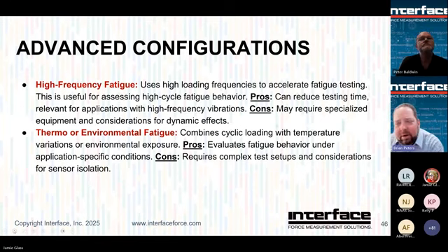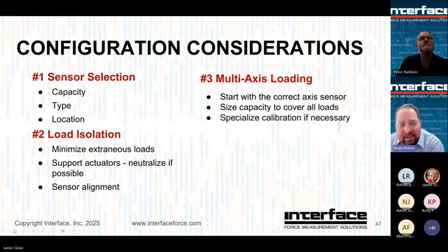So the better you can thermally isolate the sensor, the more accurate data you're going to get. However, there's certainly ways you can characterize that data. And again, application engineers are standing by to talk through that. So if you have to seal, let's say you're trying to do something in a pressurized environment, that's great. You have the sensor outside of it. Don't forget the effect of the seals or any sort of parasitic load path that might be there as a result of that.